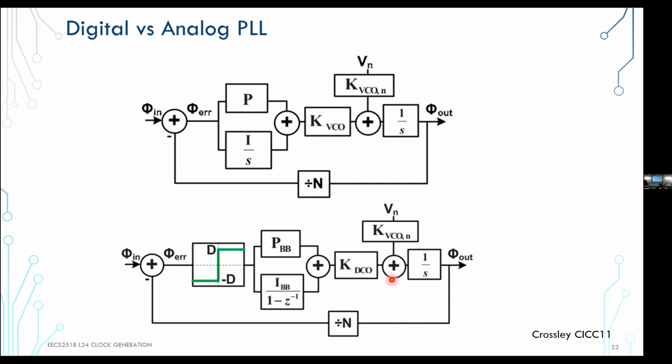Right? So I have to have some way of creating a DAC or digital to time converter. Right? That's my DCO now, because I'm changing some digital settings and the delay or the frequency changes on the oscillator. That's going to be the idea here. And then I just have a divider. So if I can do this, then all of these elements are kind of digital, except maybe the DCO. There's a little bit of stuff going on there, but as we've seen, it's inverters. If I can control them with some switches, it's kind of digital, right?